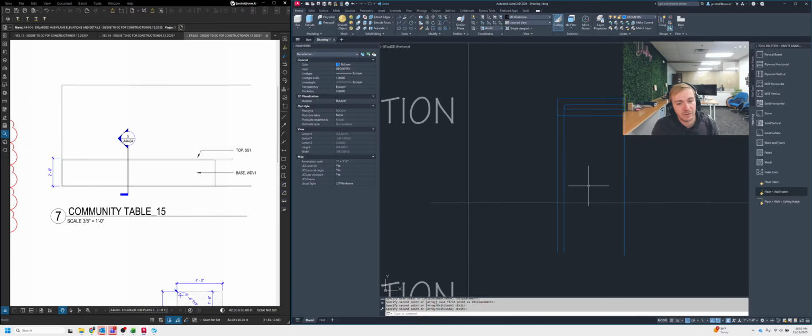Okay. So when it comes to 2 centimeter stone tops, you always want to make sure you have a subtop below that stone. 3 centimeter is thick enough that you can get away without having a subtop below. But 2 centimeter is too thin and can become brittle, and you want to make sure that you have it supported so it does not crack or break.